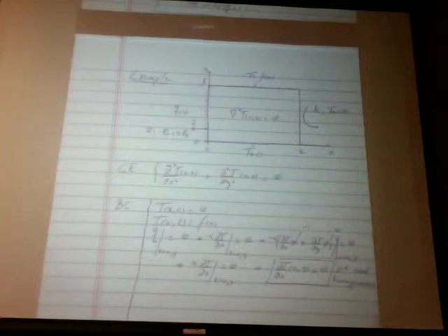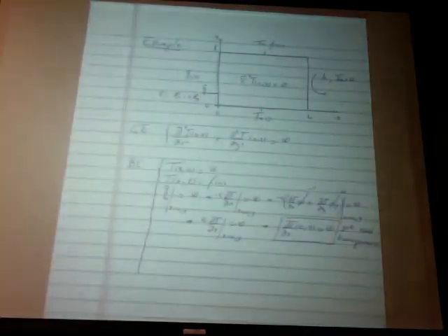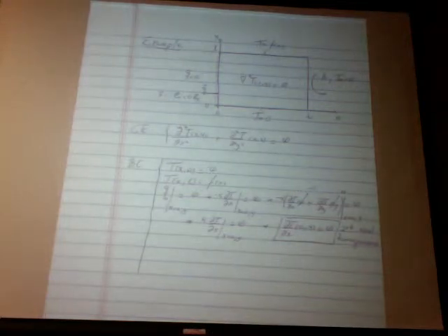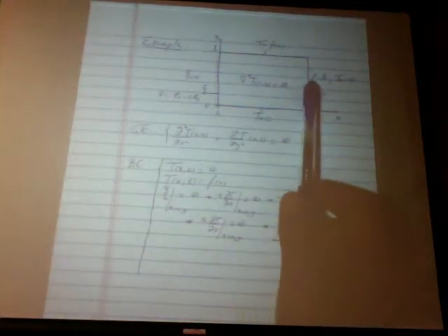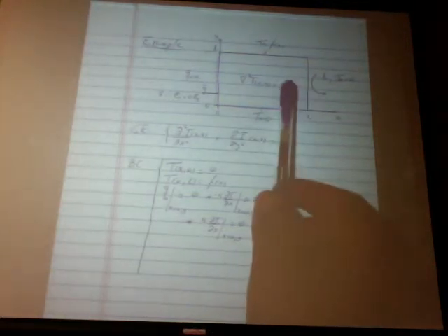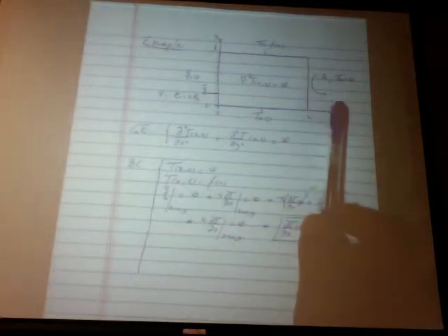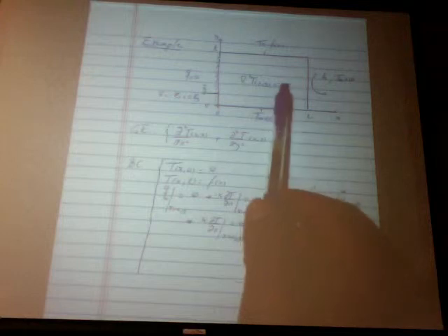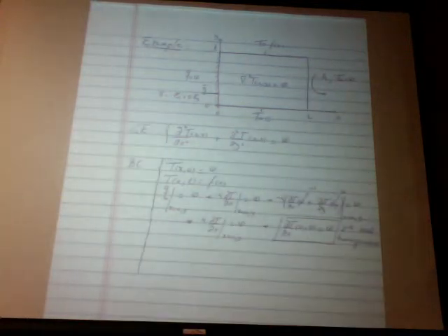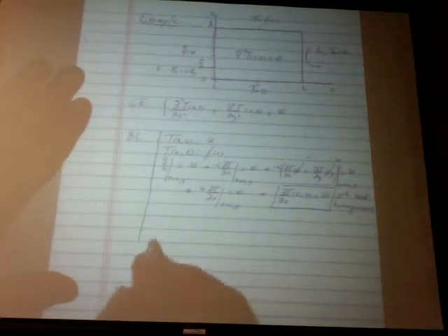All right, how about the condition on the right-hand side? That's a convective condition. What do we know about convection? Convection says that the amount of heat flux that goes in is equal to the amount of heat removed by convection, or the amount of heat going out through conduction is equal to the amount of heat going out through convection. So that means the following.